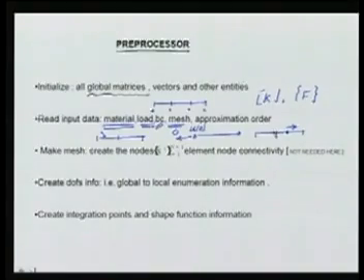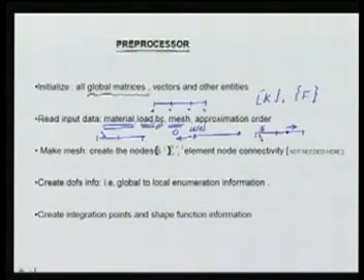So when I make the mesh, I have to give the information as to what are the boundaries of each of the subdomains over which the meshing has to be done. And then over each subdomain I have to say how many subdivisions we want. So let us say that in each subdomain we want uniform meshing. In the first subdomain I want 5 subdivisions, so it will put 5 uniform elements here.